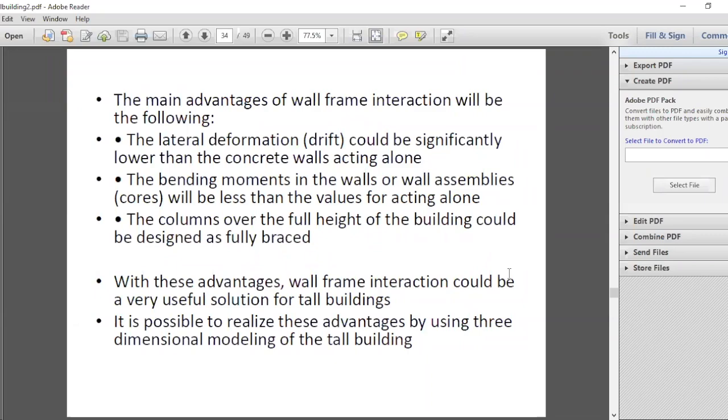frame. Now, why we consider braced and unbraced is, in the unbraced frame, if the frame becomes deformed, there's nobody to bring it back. Right? Whereas in the case of a braced frame, if the frame tries to deform, the wall will say no. The wall will restrain the deformation.